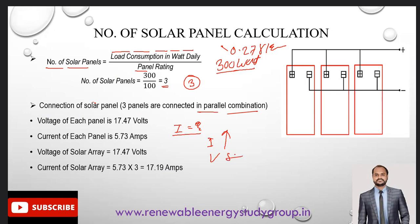Similarly, on the reverse, when we connect the panels in series combination, their voltage will increase and the current will remain the same. So if I want to increase the current in a system, we have to use the panels in parallel combination. And whenever we want to increase the voltage, we can use the series combination.